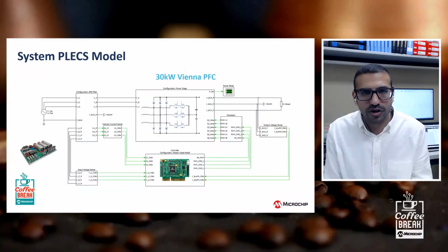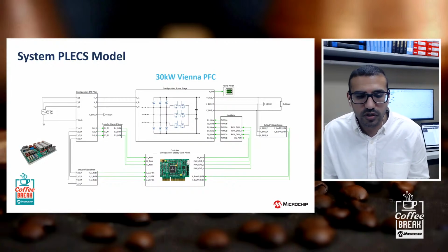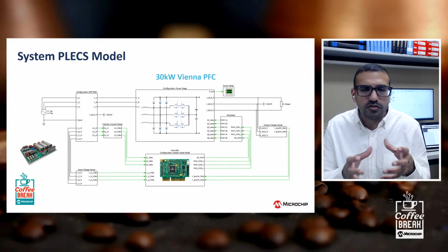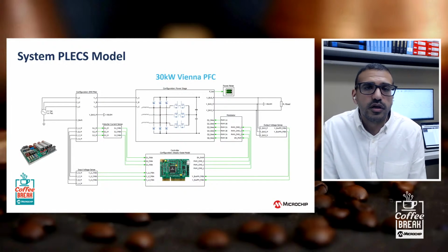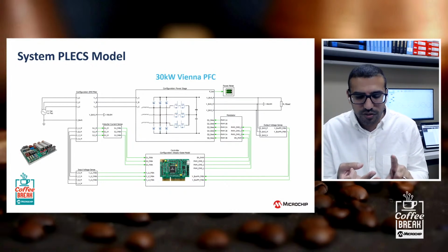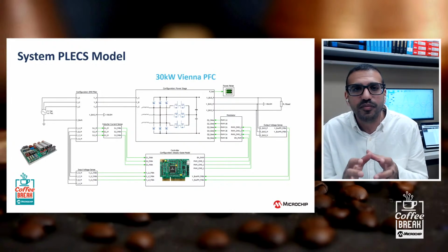Yeah, we work with a company called Plexim. So we have a design of their Vienna PFC using Plex. Now, Plex, if you're not familiar with it, is a power electronics simulation tool meant for simulating power electronic circuits and larger power electronic systems. It's actually a multi-domain tool. So you can simulate the electrical domain, the controls domain, the thermals domain, magnetics domain, and the mechanical domain, all 5 of them simultaneously. So it's a very powerful tool.